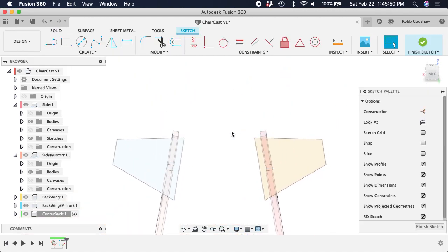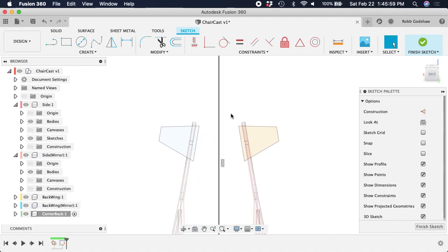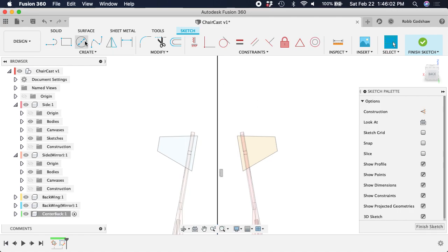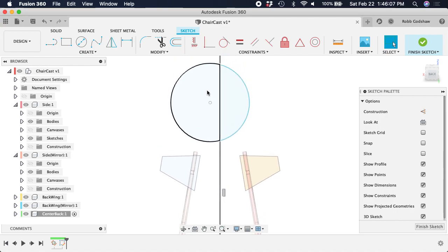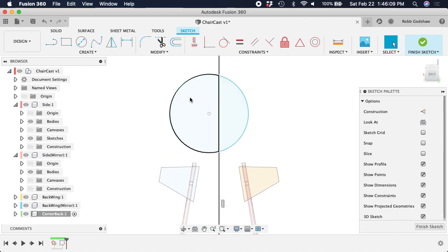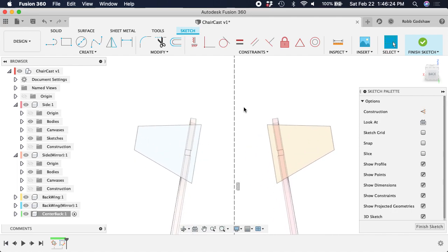I'm going to create a sketch here. I'm going to draw a line from the top down. I'm going to make that into a construction line. So right now this is a regular line. And if I draw a circle here, you can see if I mouse here, it's like, oh, I have a half circle, a circle segment and a circle segment. But if I make this into a construction line, it then ignores that line for purposes of selecting regions, which is important because when you're extruding things, the last thing you want is to have to click a bunch of different divided up sections.